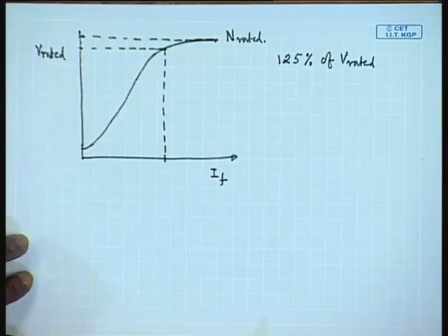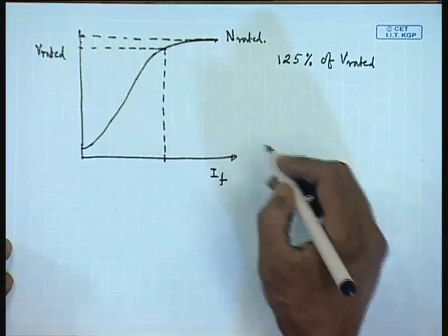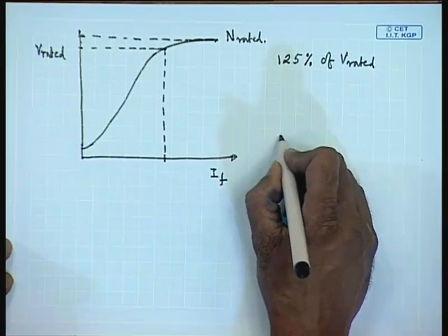However, as we have mentioned earlier, the O.C.C. for any other speed can be obtained by multiplying the O.C.C. of the generator at rated speed by the ratio of the speeds. However, it is more important, at least for a generator, to find out what is called its output characteristics or the external characteristics. This one is the open circuit characteristics or O.C.C.